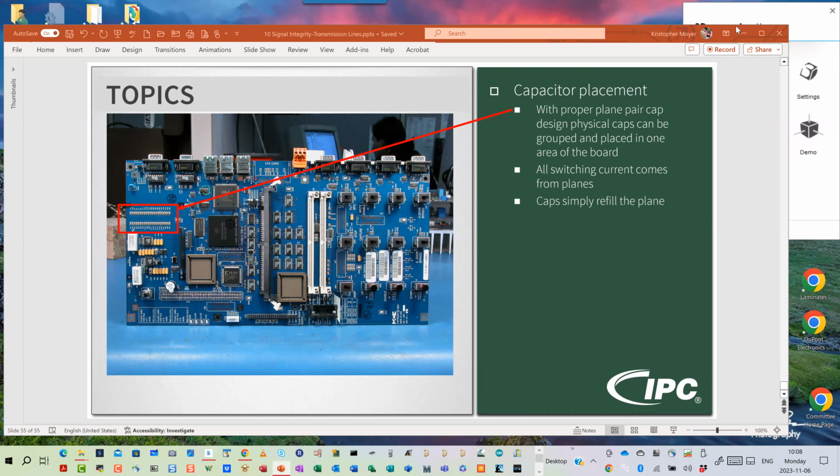Right. Power is a different beast. That's where you have to make sure about the routing that we've been talking about. You've got the total power. In this case, yes, you're taking 60 watts of power in, for example, but during an instantaneous switching event, let's say it's just 32-bit, 64-bit, even if all 64 IO switch at the same time, the speeds of those things are so fast, such a momentary instant in time, that this physical capacitor, because of its lead inductance, still can't respond.